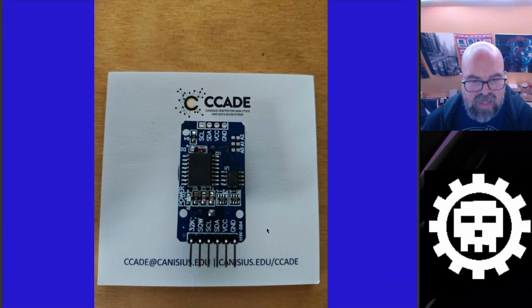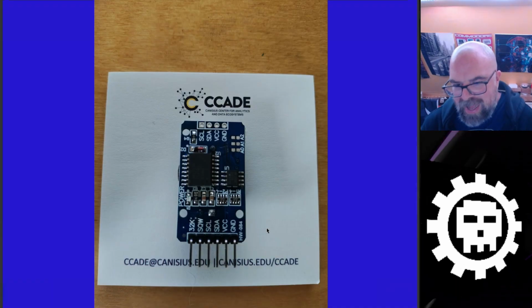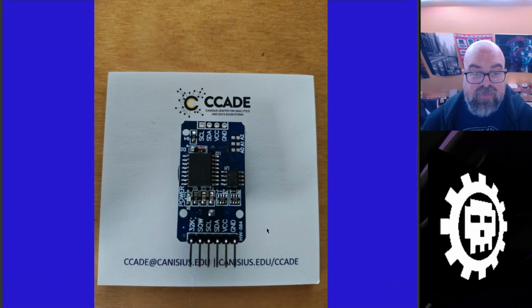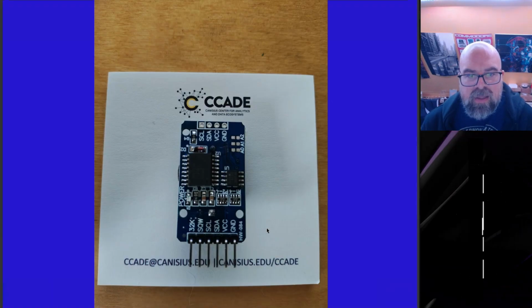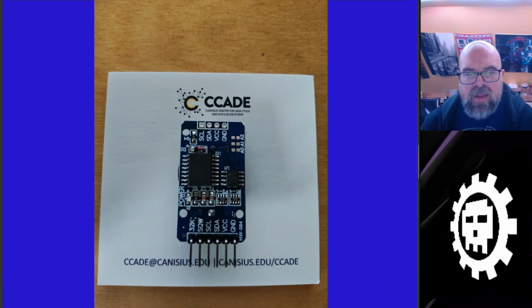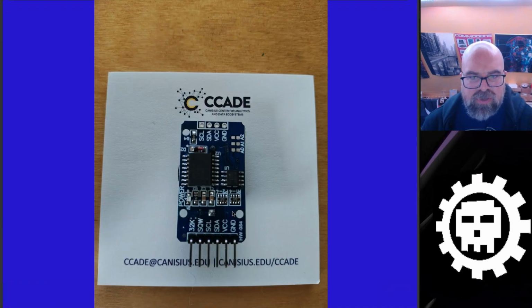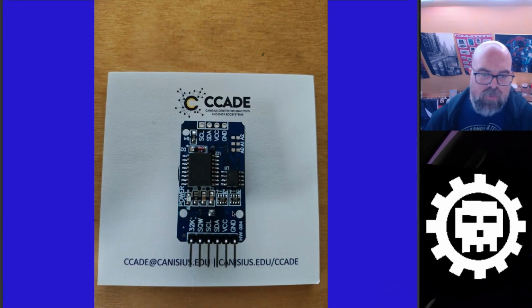Because any more than that, and it will activate the charging circuit and attempt to charge your unchargeable battery, and could lead to hardware damage or problems, possibly even a fire. I don't know. So just be aware of that. There is a charging circuit on here that you can desolder or you can break. I'm not sure where exactly it is. You can check the documentation for more information on that, but the easiest thing to do is just make sure that you've got the proper variety of coin batteries set up.